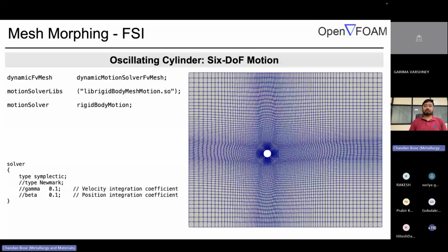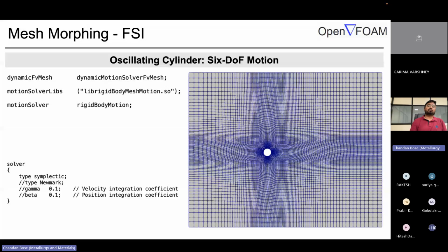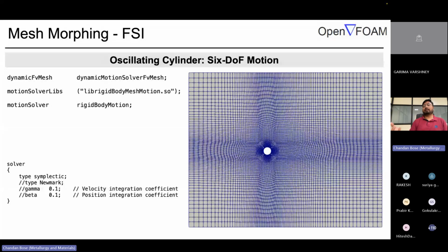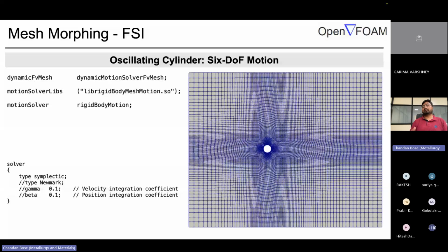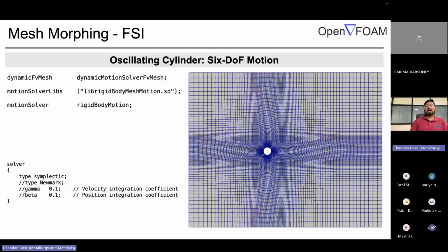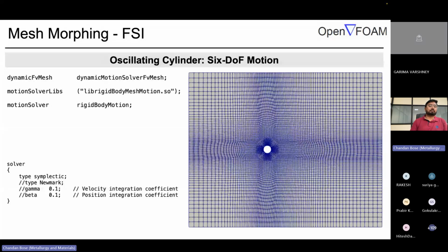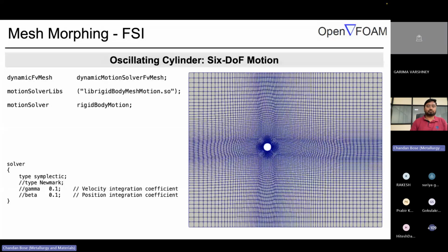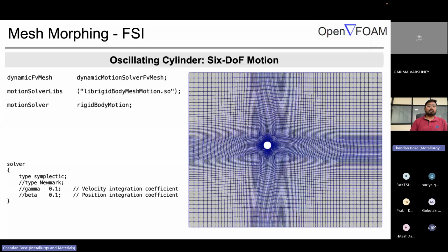It goes in a coupled manner where we have to solve the Navier-Stokes equation to get the aerodynamic or hydrodynamic forces, and then we have to apply these forces to calculate the displacement through a structural governing equation, etc. And then it should be coupled either in a weakly partitioned approach, a strongly partitioned approach, or a monolithic approach, whatever it is. Right. So this is probably clear to you.